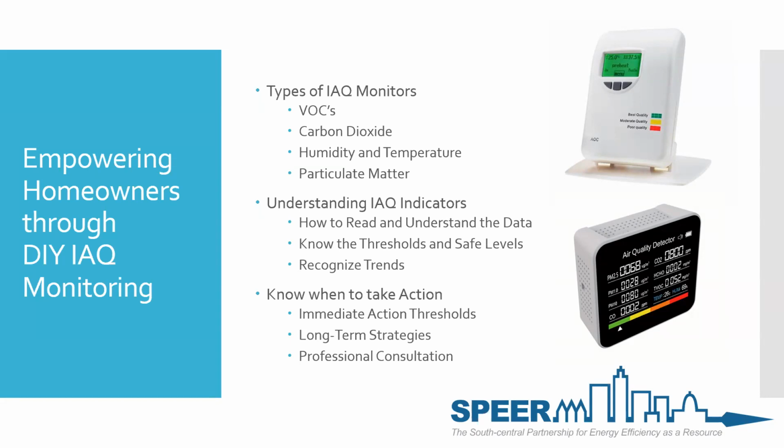So is it an immediate action? If you have a lot of CO2 or CO built up inside the house, did something happen in the home that requires immediate action? Opening windows, doors, turning on air purifiers, evacuating the house? Or is it long term? Recommendations for consistent readings that elevate pollutants might indicate that the home needs improvements, such as upgrading ventilation systems or replacing certain materials.